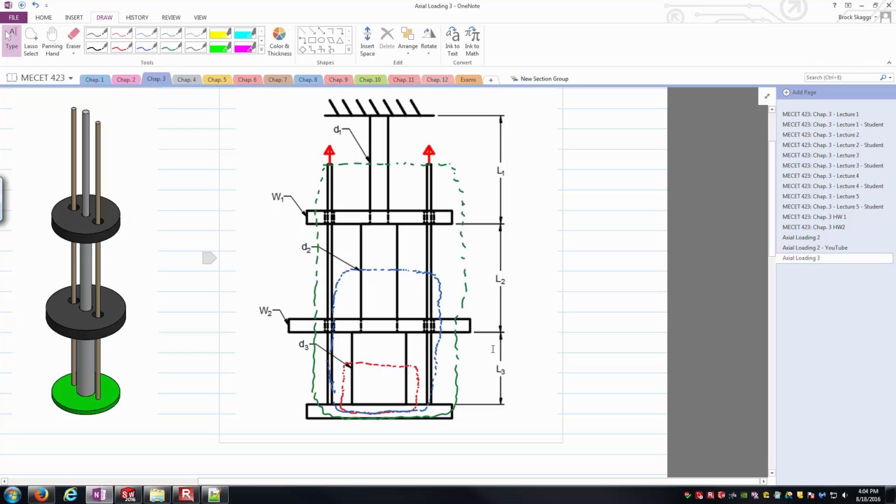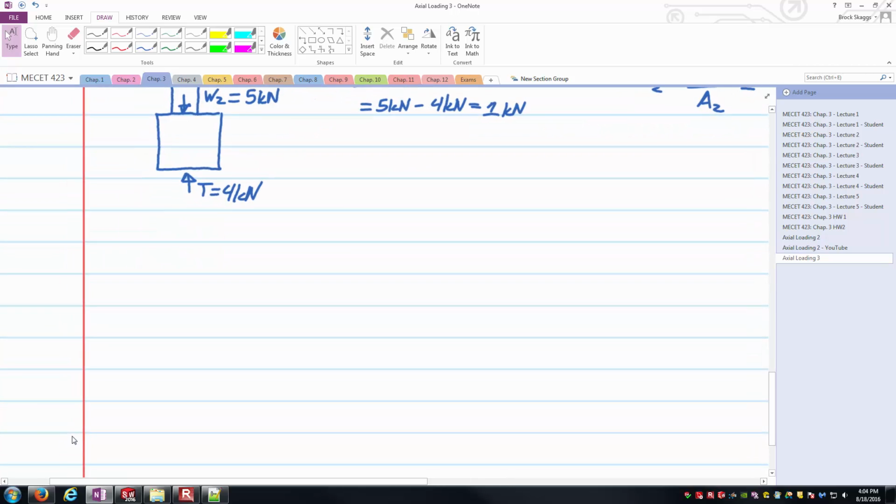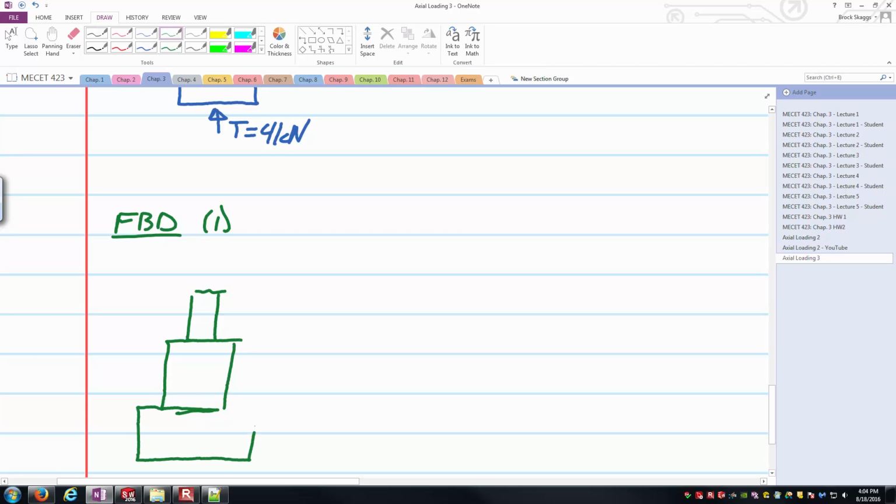And so now we've got more of the step shaft than we did before. And so here I'll come back down, again drawing our free body diagram of, now, section 1. And you can see how I've talked about this being very mechanistic here. We're just going through the motions at this point. There's the bottom half of section 1, here's section 2. Excuse my horrific drawing there. And there's section 3 there. Again, let's assume that there's a non-zero axial force here.